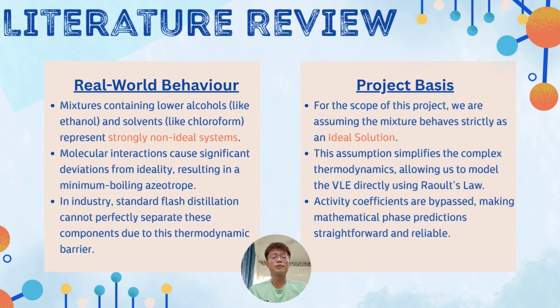This is the literature review for our project. In real-world behavior, mixtures containing lower alcohols like ethanol and solvents like chloroform represent a strongly non-ideal system. It is because the molecular interactions cause significant deviations from ideality, resulting in a minimum boiling azeotrope. So in industry, standard flash distillation cannot perfectly separate these components due to this thermodynamic barrier.